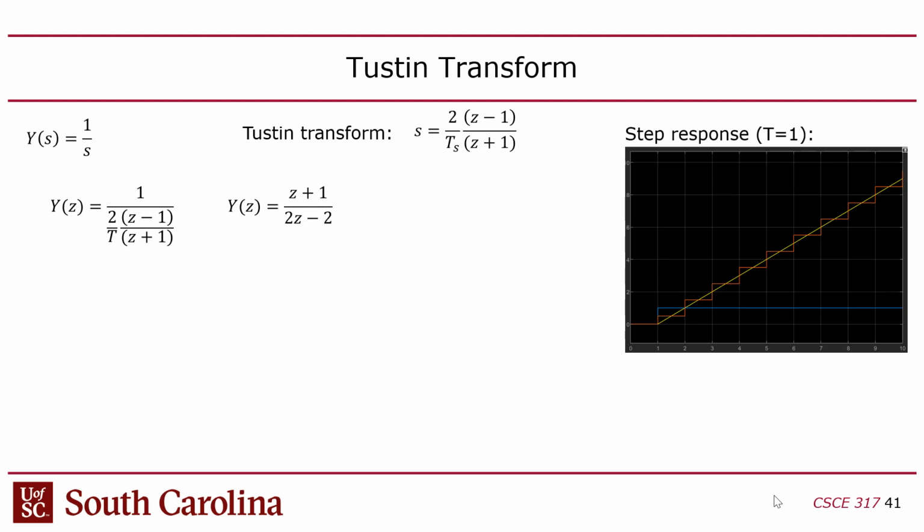So the model is in the S-domain. What's the controller? Is it S-domain? Well, sometimes, yeah. That's one way to do it, is you design a controller in the S-domain for a physical world that's in the S-domain. But then you have to deploy it on a computer, so you convert it to Z domain. So the question is, how do we convert S domain to Z domain? Is there a way to do that?